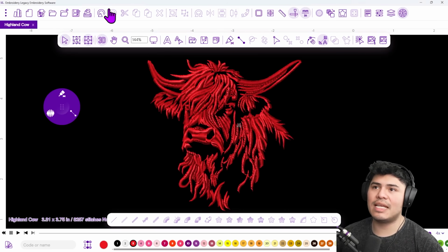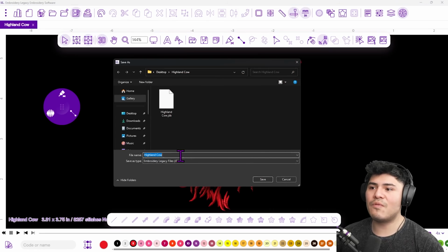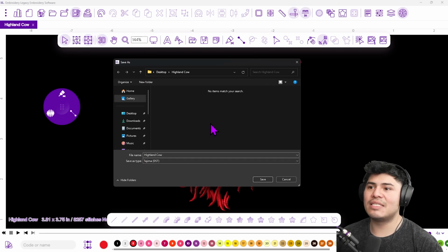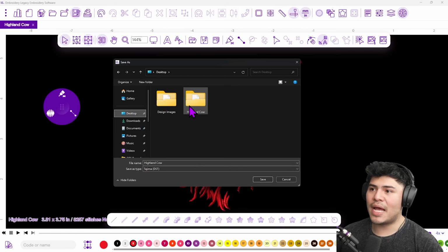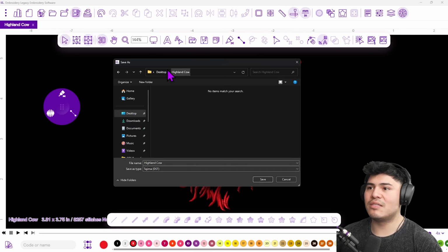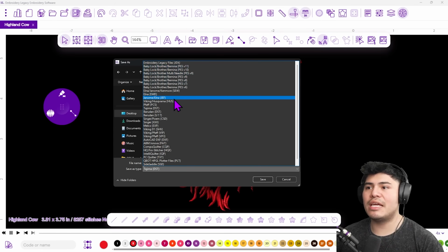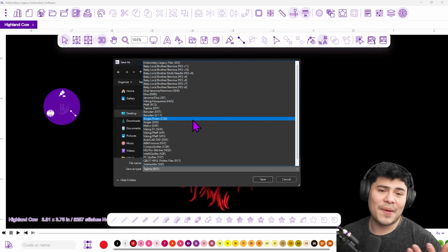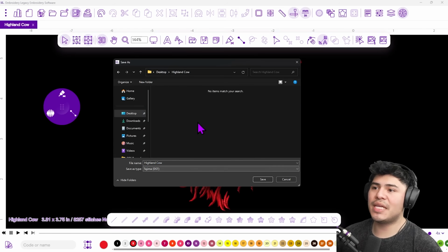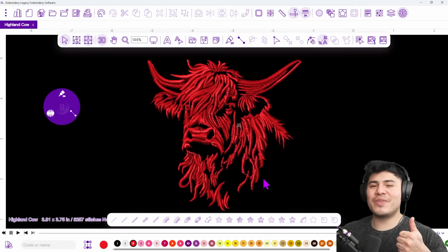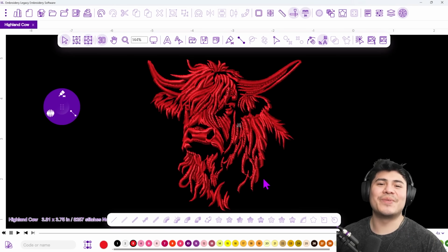So I'm clicking save and now I'm just going to save it one more time, but I'm going to save it as a DST because that is the Tajima format that I'm going to embroider this on. So I'm just going to save it under the same folder as the DST. You can save it as a PES file, a JEF file, an HUS, depending on the machine that you have. But for me, it's Tajima. So now that I click save, I'm going to go embroider this, guys, and I'll come back to you with the result.